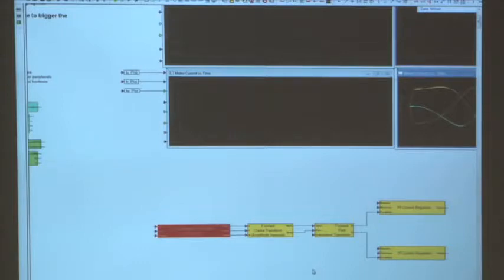Now, for the D-axis, assuming we don't want to do any field weakening or anything strange, what do I want to set the reference value for D-axis current to be? 0. So let's go up here to the tool palette, and there's a little 1 with a square around it. That's my constant tool.